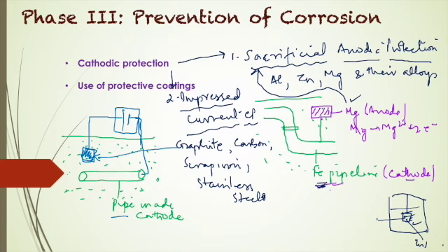If the pores, breaks and discontinuities are there in such a coating, the corrosion of the base metal is speeded up. This is due to the fact that exposed metal acts as anode and the coating becomes the cathode over there, right? So a galvanic cell is set up and an intense localized attack at the small exposed part through those pores and pits and cracks occurs.